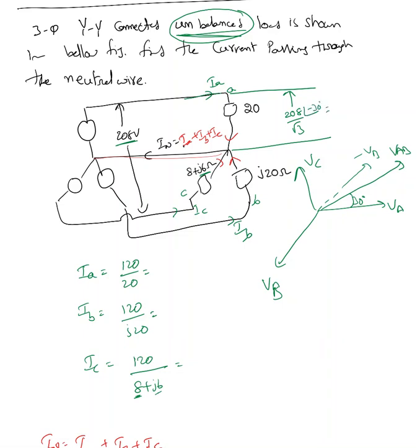Now, in the previous videos I never considered this angle. Here I'm considering that angle because this is an unbalanced load. When it becomes an unbalanced load, to find the neutral current, that angle is definitely going to have some impact on our current magnitudes and phase angles. Actually not magnitudes, mostly phase angles. So that's the reason I need to consider that negative 30 degree angle.